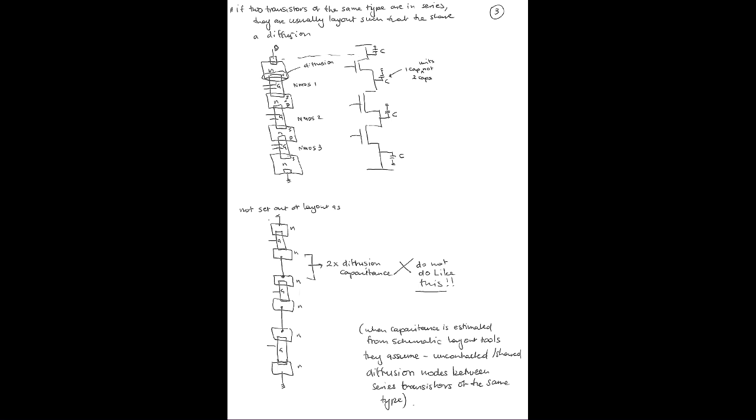And in this particular case, what I'm saying is, for one of the simplest of circuits, which is an inverter driving three other inverters on a 65 nanometer CMOS process, you can get 66 gigahertz. And I guess being at 66 gigahertz, I tried to make a joke, if I remember correctly, that it's very high speed electronics. That's why the name of this course.